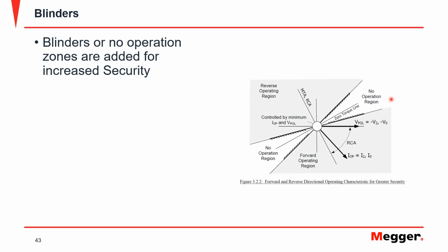You have to secure your system, and you have to perform the proper short circuit study, and not just the short circuit, but also the load flow study, and compare them to determine whether you are going to have issues with the zone of operation, and then you have to decide.